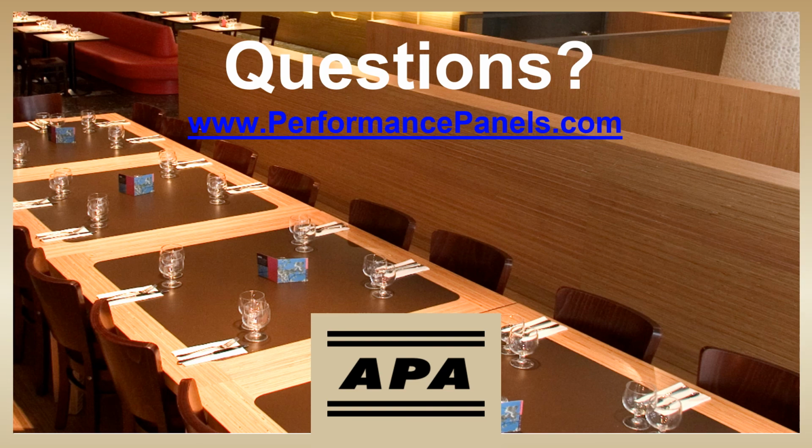So if this example was a 4-ply panel, the 2 plies in the center or core would have their grains running in the same direction. So if 2 adjacent plies have parallel grain, we call that a layer. So this 4-ply panel has 3 layers. If we did exactly the same process on a 5-ply panel, all of the plies would be perpendicular to the adjacent ply, so we would have a 5-ply, 5-layer panel.